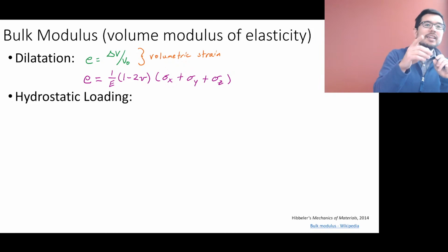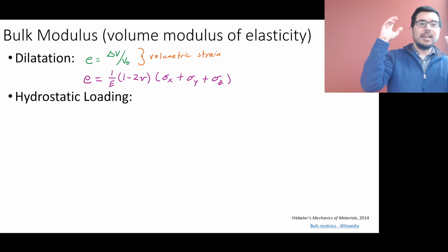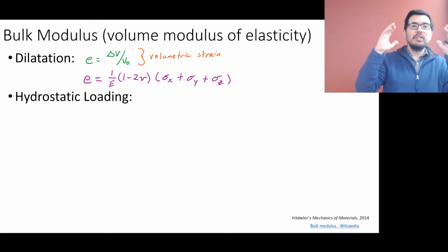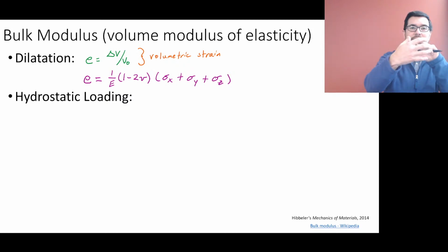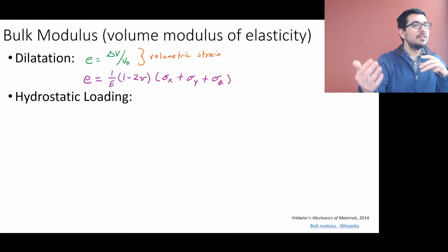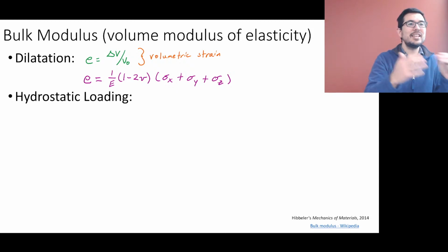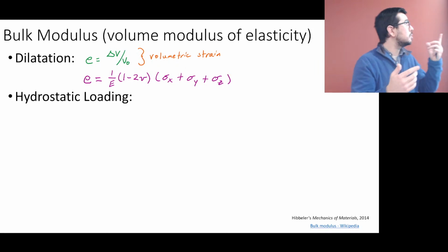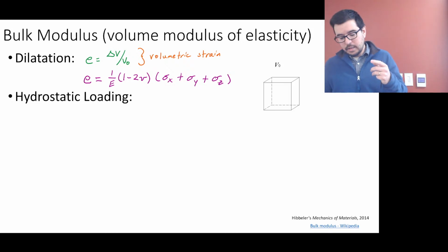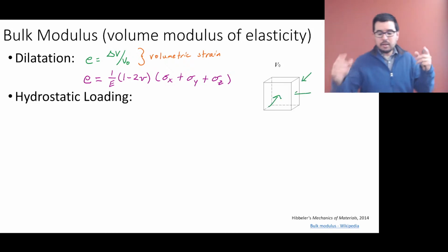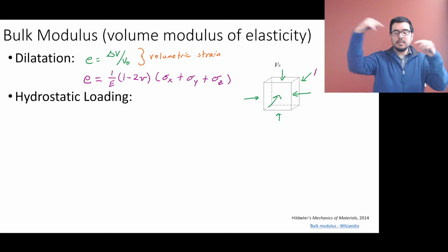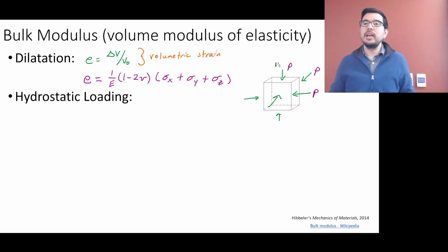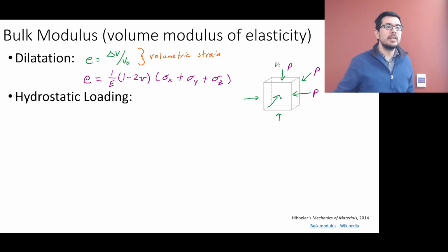Yes, right. The object is going to feel the pressure on all sides, like you said, and you get the idea, right? Pressure has units of pascals. Stress has units of pascals. Well, what do you know? I can just substitute in all of those P's into the sigma x, sigma y, and sigma z.